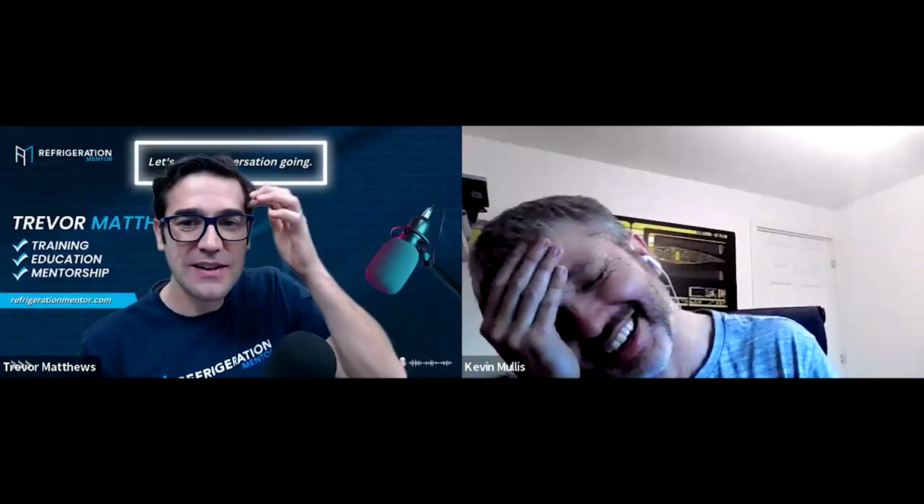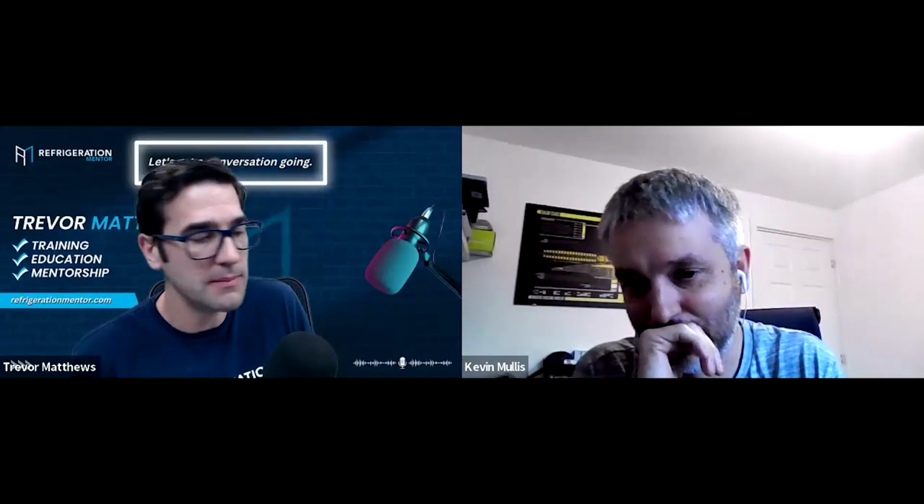That's one step away from the TXV 2.0, isn't it? It's on the Schrader. Well, there are ball valves in front of all those now. There are no Schraders. So come on now. Right. You know what I mean? But that's it. It's just getting them to realize, every time I'm doing a CO2 program, I'm telling them, do not just shoot that gas to the atmosphere. It's still a GWP of 1.